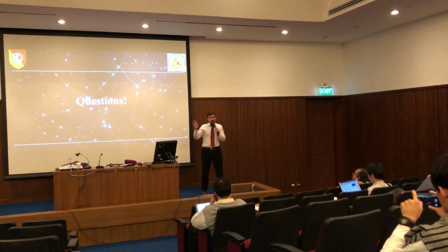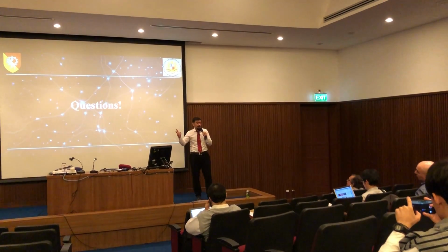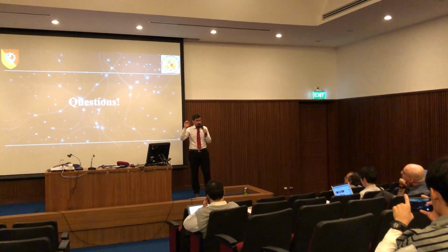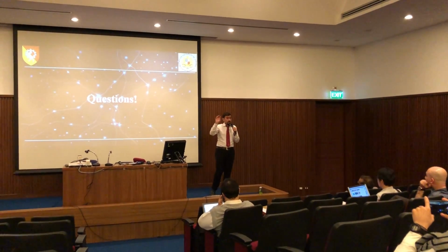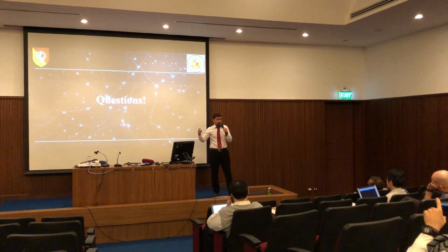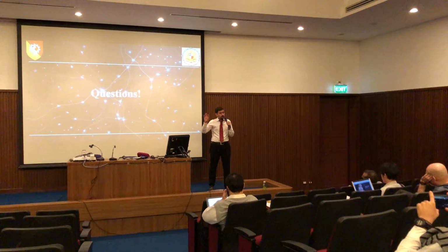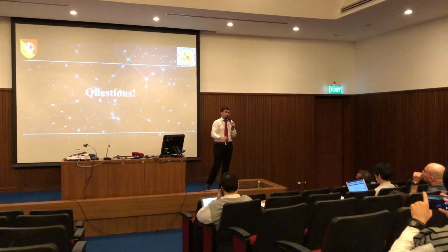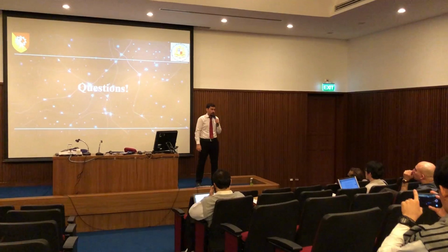The calculation is two steps. First subtract the pixels. When that subtraction result is greater than a certain threshold, it will trigger the second process, which is sending the coordinate at that moment. If it's not, there is tolerance for noise, if that's what you mean.